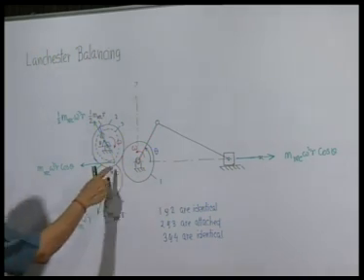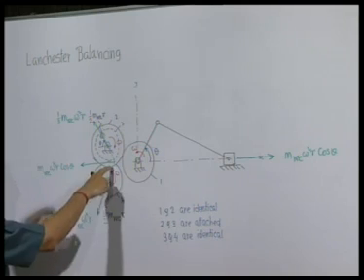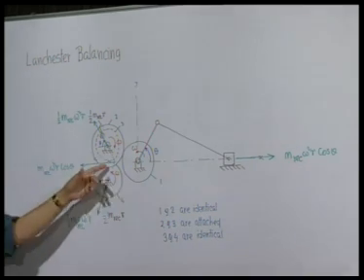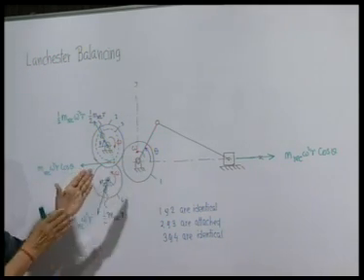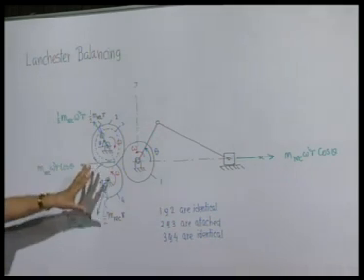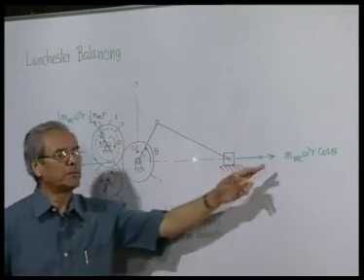As you can see, the resultant of this and this will be in this direction, the y component of this and y component of this will be neutralized among themselves. So, this way, and you have to also keep in mind that they must be aligned, so that they do not produce a couple. So, in this gear system, this unbalanced mass system can completely neutralize the primary.